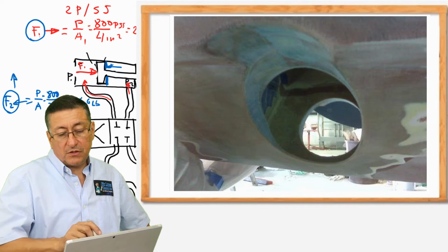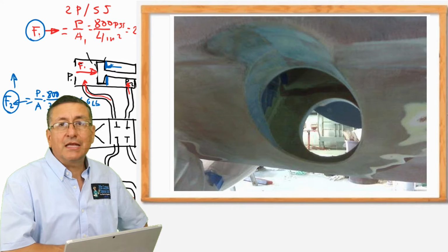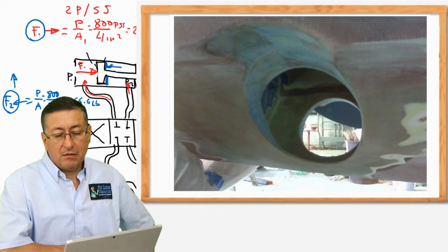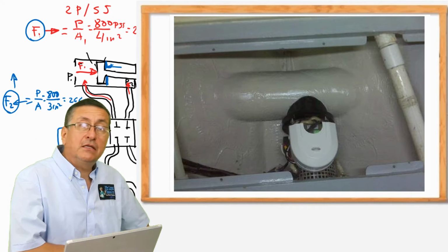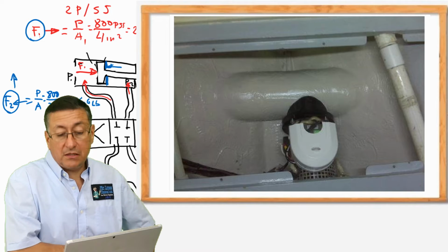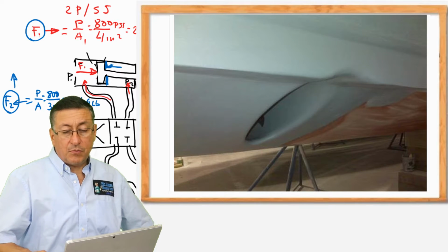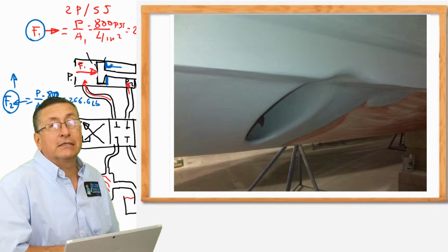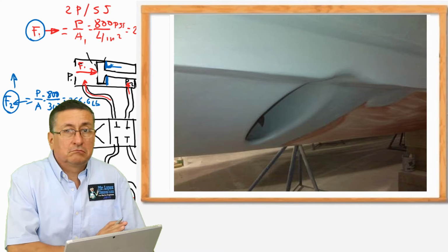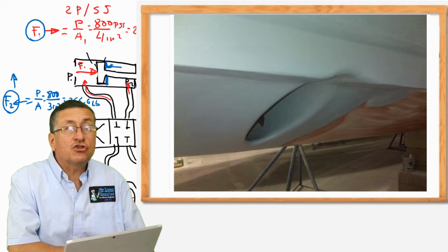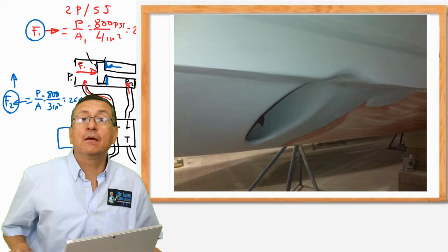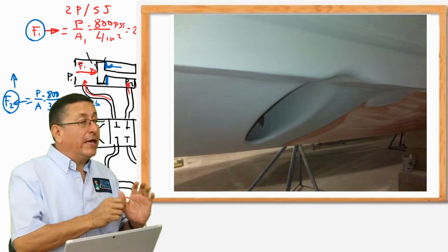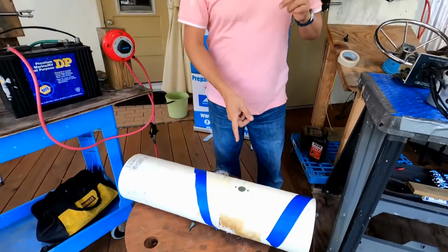And outside right now, this is before the tunnel is installed. Prefer to sand the area and remove the paint before you laminate. And after that, when you laminate, you paint properly internally, and you paint properly externally, exactly like this. Now the hull is finished, and you are ready to install the bow thruster in this way. Now the tunnel is properly installed in the boat.